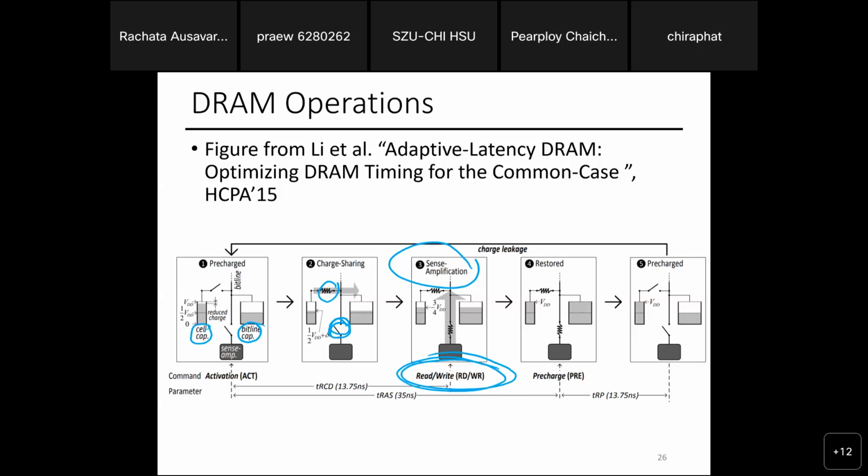Now, once I finish reading, I have things in the row buffer. The next step is I have to pre-charge. Pre-charge basically means this. I have a really filled up tank, in the bit line capacitor. It's filled up. Like look at figure part 4. It's filled up. I need to make it 1/2 again. How do I do that? I disconnect everything and wait until it drains to 1/2.